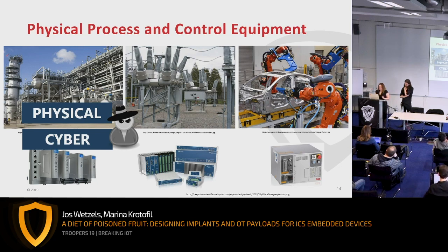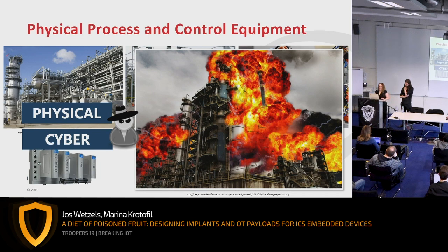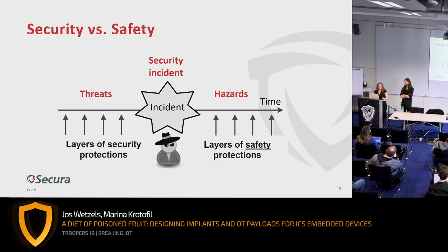And in the mass media, it is typically believed the attacker wants to make something explode. The point is, it's not that easy to make something explode. Why? Because we have safety. Even if the attacker is able to cause some incident and maybe close all the valves and pressure is growing, there are layers of safety protection which will not allow the attacker to do so. There will be pressure relief valves which the safety system will open.